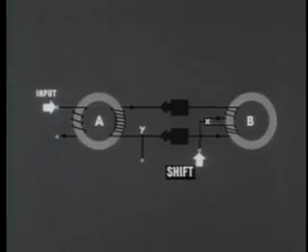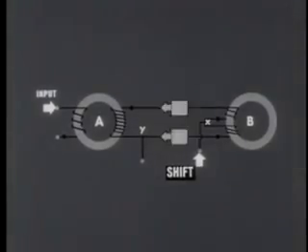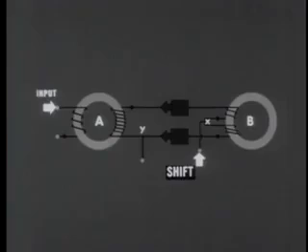Schematically, this loop resembles the one we've just been studying. There's the same split winding arrangement to which the shift pulse is applied, the same diodes placed so they oppose the flow of current out of either side of the output winding, and the same outlet connecting into the loop at the non-dot side of the output winding. The differences are all on the left. We won't be using the same kind of output winding.